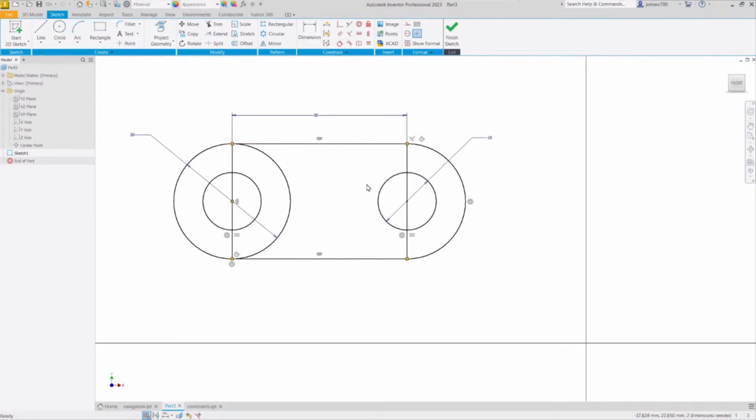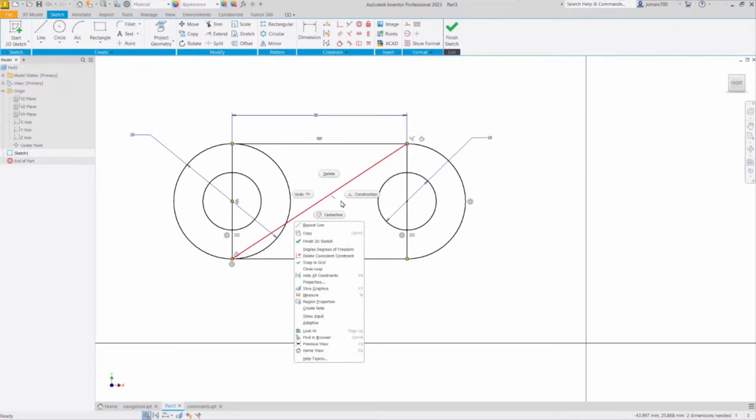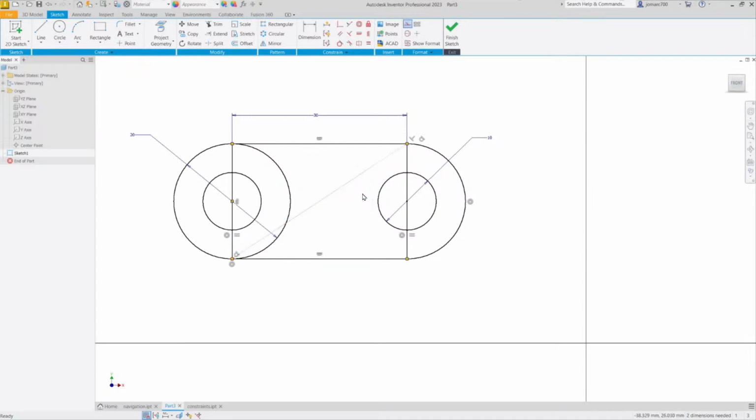And for the center of the sketch to be aligned with our center point, we need to create a new entity. And that entity, I am seeing it should be a line. So I'm going to hit L for line, creating a line from this point, left click here, moving up to here, double left click, hitting escape. And because this line serves as a construction line or helper, I'm going to select this, right click, and turn this into a construction entity.